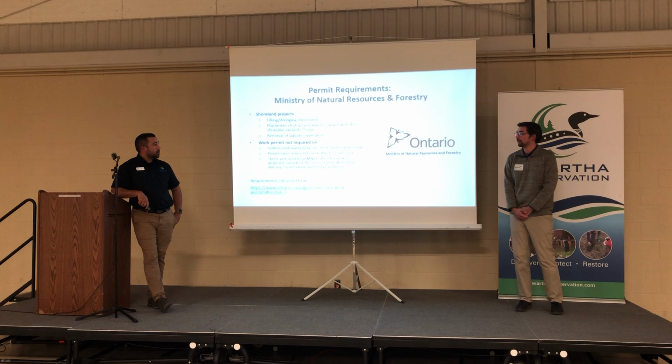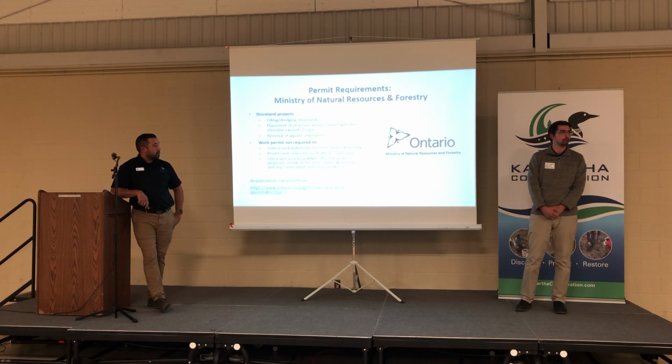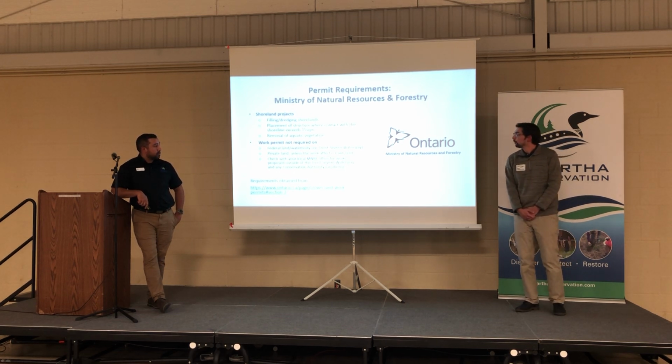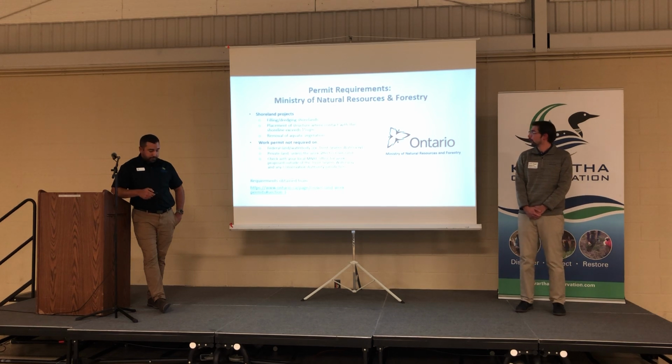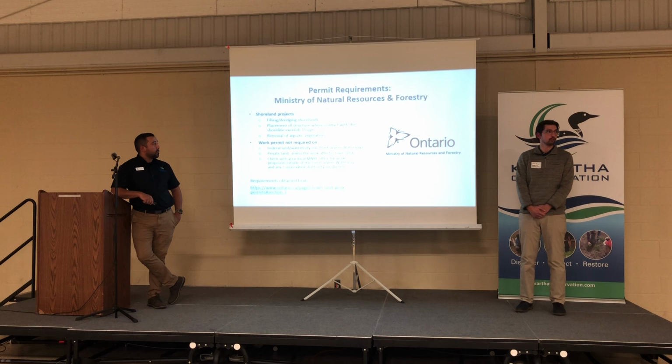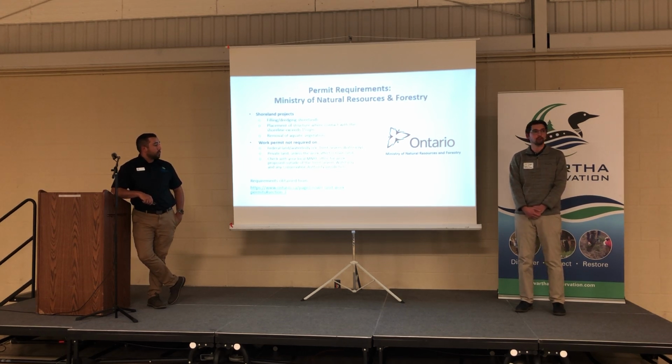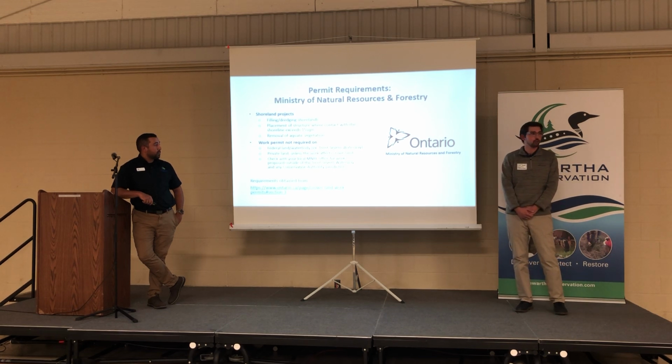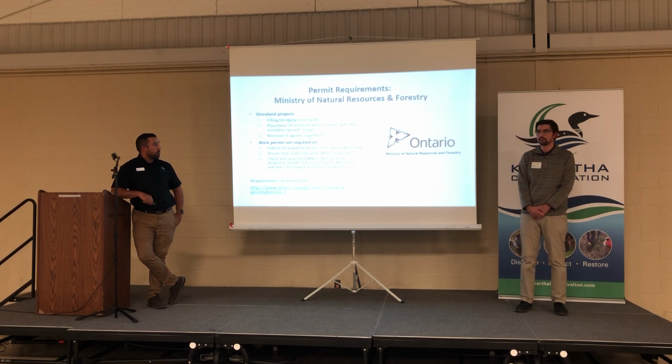There's also the Ministry of Natural Resources and Forestry to keep in mind when you're looking at developing. For shoreland projects, you may require a permit for filling or dredging shorelands, placement of structures where the contact of the structure and the shoreline is greater than 15 square meters, and the removal of aquatic vegetation on your property. For more information, we really encourage people to check with their local MNRF office to determine if a permit or approval is required from them.